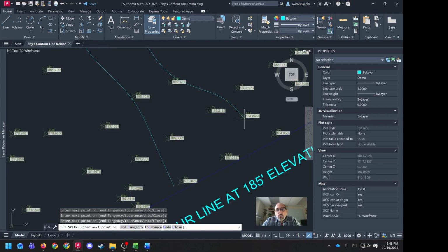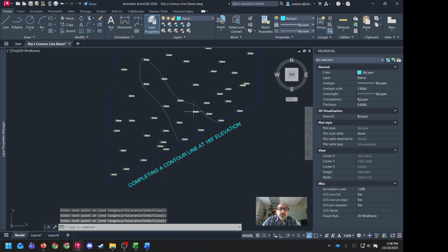Next, 184.8, so really close here. That's, again, 2 over. This is just 1.2 under. And so it looks like we've got our last point. 185 is beyond both of these. We're going to be real close to here. And that would be our first contour line.